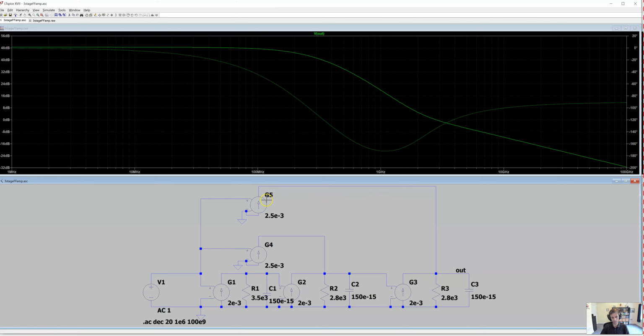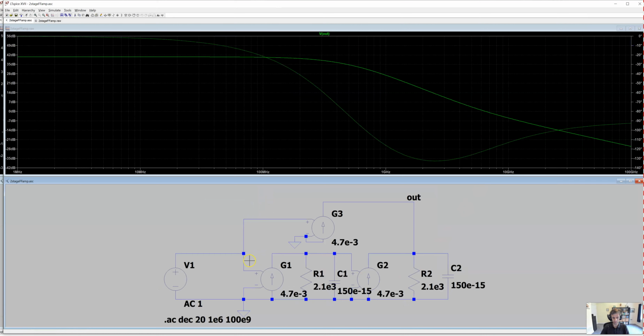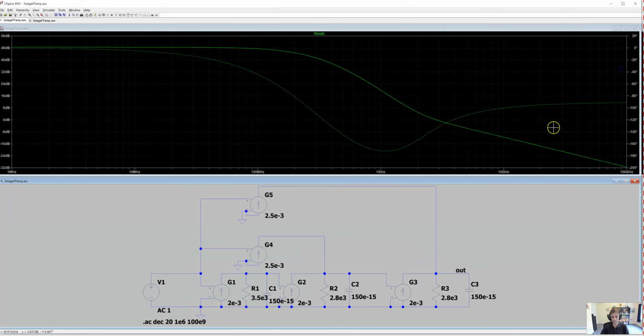So this is interesting. Another thing I'd note is that if you sum together all the transconductances, all the GMs, you've actually got a lower total transconductance, despite the fact that there are now 5 transconductances, than what was required to meet the same specs with a two-stage amplifier. Even though we're in a technology with a lower intrinsic gain, we're able to go to a 3-stage feed-forward amp, and assuming that all the bias currents are proportional to the required transconductances, then you may end up with a lower power consumption for this 3-stage feed-forward amp meeting similar specs, in spite of the fact that you've got lower intrinsic gain and you need more stages.